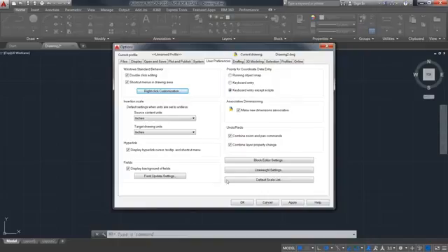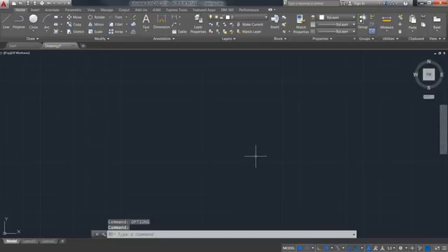And another thing I wanted to get into before we get into actually drafting things is the dynamic input. The dynamic input is when you start typing, you see the little pop-up thing that appears right by the crosshair. That's your dynamic input. And it will not only display the commands that you're typing in, it'll also show the various prompts that are subsequently resulting from those commands that you've started. And it'll show you things like the angle of the line that you're drawing and other things.